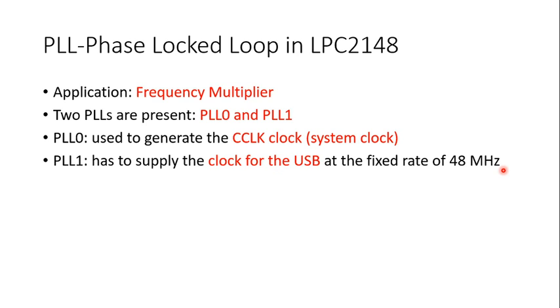Okay, so we are going to study the phase lock loop present in LPC2148. There are two PLLs present in the 2148. One is to generate the system clock and the second one is to generate the clock for the USB.